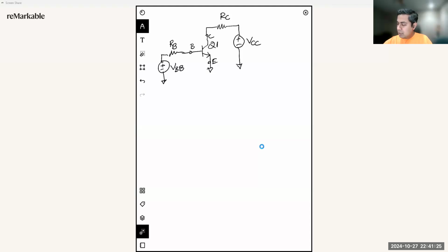When you hit P, or open the parts window or component window, write down NPN to instance this BJT in your schematic, and it usually is denoted with Q. Once you place your instance, your symbol for BJT, it will usually start with Q1 or Q2. When you first instance a BJT, it just says Q1 and then NPN.